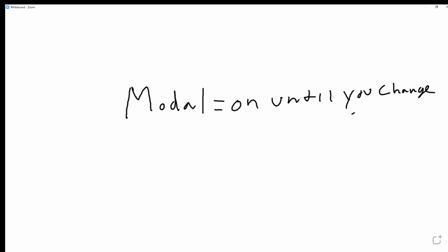That means if you are working around a workpiece, let's say, we'll talk about our first initial code, this would be G00, which is a rapid command, that this is on as we go around a workpiece. If we're just moving around a square, you don't need to put G00 on every single line. You just need it for the first one and it'll remain on the whole time. That's what modal means.